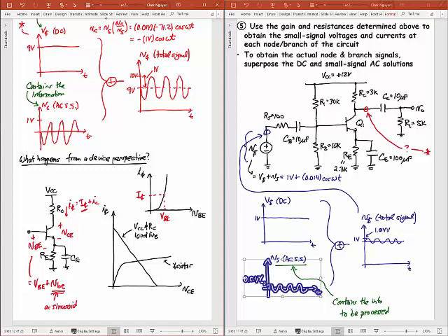So that is my bias point right there for this whole thing. And so what do I do in this? I'm going to wiggle VBE, right? I put an input signal into this, and that input signal is essentially just wiggling VBE. Okay, and I'm going to wiggle VBE within a certain amplitude, right? For this case, 14 millivolts was how much I was wiggling it.